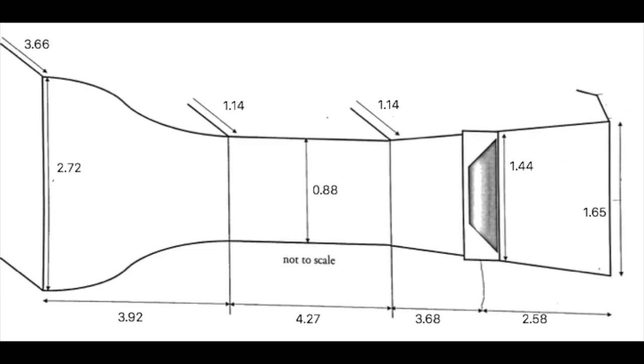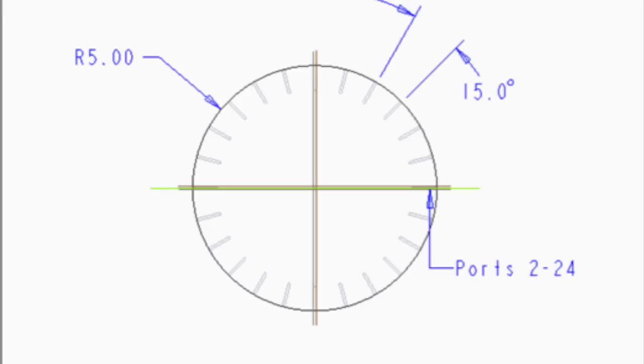The cylinder flow experiment was conducted at Cal Poly's own low-speed wind tunnel, located in Building 41. The test section for this lab was modified to hold a specialized cylinder against the walls of the test section. 24 pressure taps were mounted in the surface of the cylinder at 15-degree intervals to each other and were connected to a Scanavalve Radbase 4000 transducer bank.